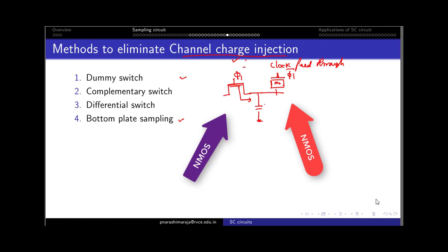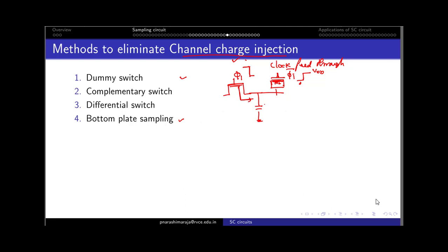So the moment I turn off the device from on to off, this device has to be turned on by applying a gate potential which switches from 0 to VDD. The moment it reaches VDD, it requires the channel to be created over here, and I'm going to grab these charges in order to build the channel. Let us first assume certain charges that are moving here.